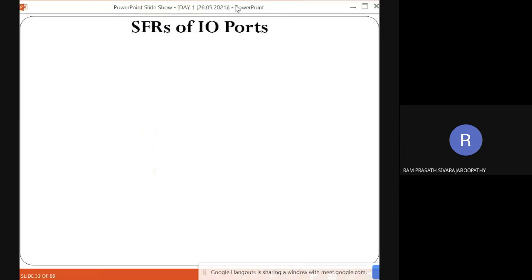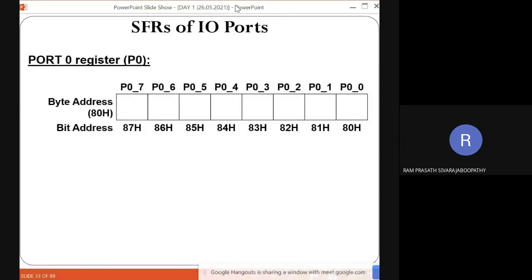In embedded C programming, we may not use a variable with a dot symbol. A variable should not contain a dot symbol in between the naming. So we use the underscore symbol instead of the dot for addressing the port pins. Is it clear to everyone?